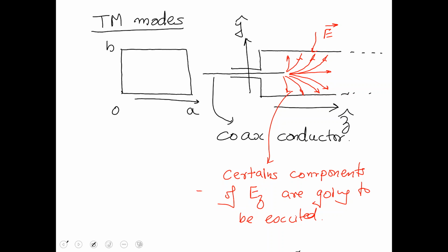In the XY plane, you have this conductor in the center. That conductor shows up as effectively like a point over here. So I have made a hole on the starting point of my waveguide. I've made a hole and I've put a conductor through, and I'm taking a cut of the XYZ plane. So that conductor is going to look like a point, and thus the H field which we are going to generate is going to loop around this conductor.